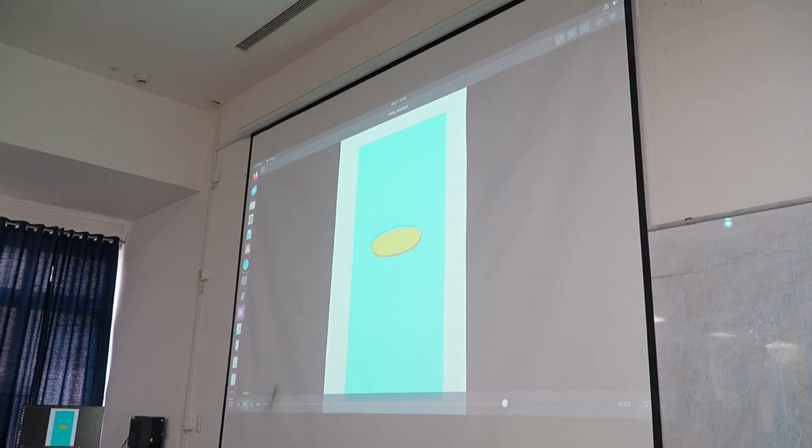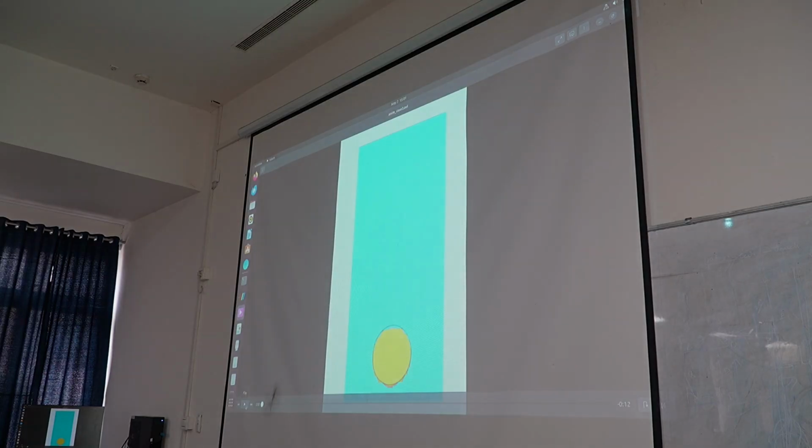For the plot you have made between velocity and time, you have tracked the centroid. Yes, either I can track the centroid or I can take the average value of velocity within the bubble. I can give a cutoff value that alpha less than 0.5 or less than 0.9, which will represent purely the air domain. ParaView will give you the average velocity only in that portion. That post processing you can do in ParaView.